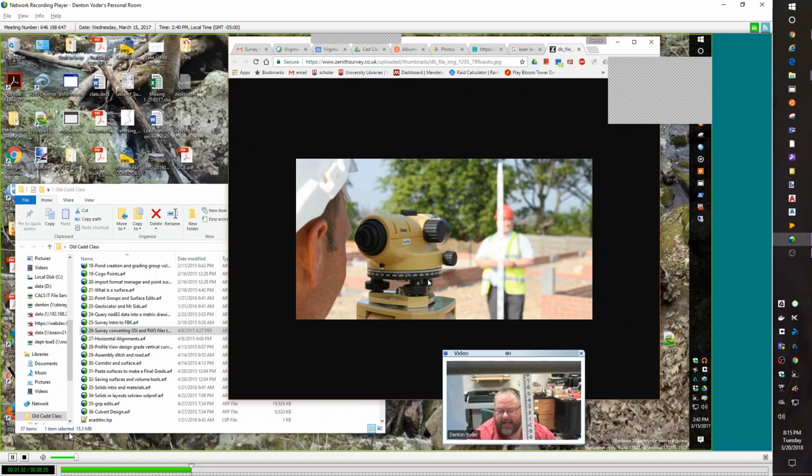So if you have any known elevation, you can put the ruler on the known elevation and look at what number you have on the sight glass. By adding the known elevation plus the measured elevation, you now have what they call height of instrument. Now you can measure any other place on your job site, and you subtract your measurement from the height of instrument, and that will give you the ground elevation at that point.